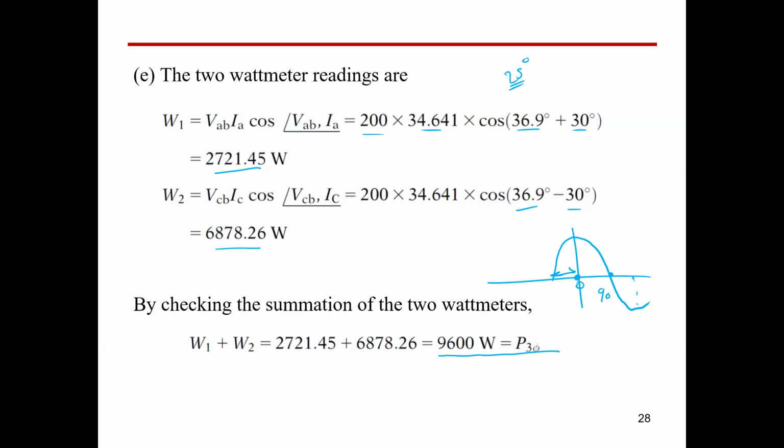So please consider the angle with the negative sign, and if you have the reading of the wattmeter in negative sign, please consider this negative sign as well. This doesn't mean that the power is reversed, but it means the wattmeter is not connected to a single phase, so it's not the power absorbed by one phase. It's a different relation now.